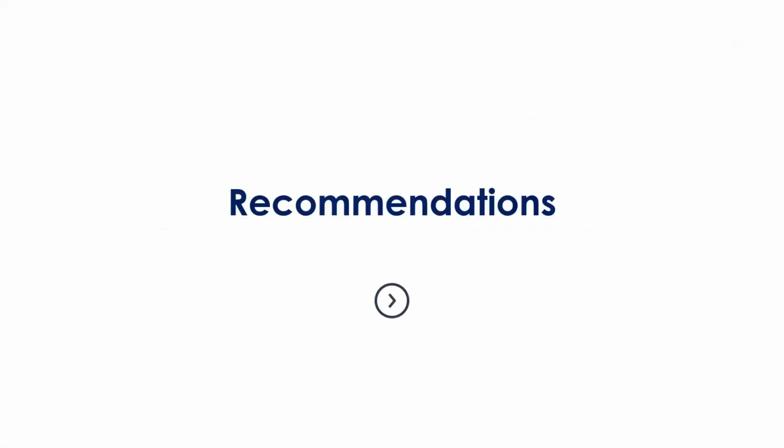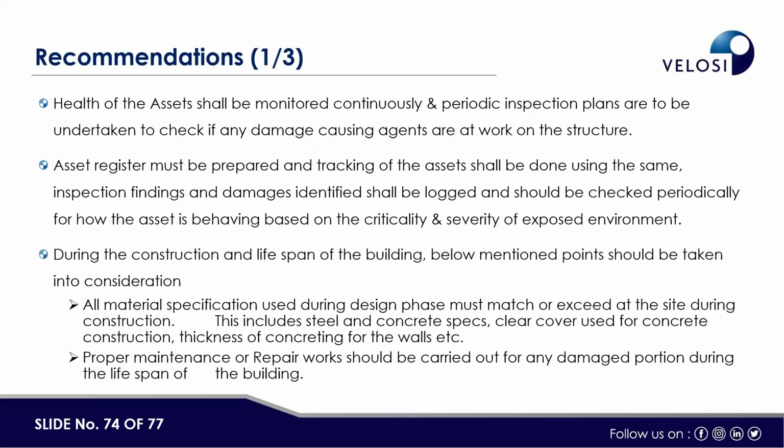Now for the study which we have conducted, these are the recommendations. The health of the asset shall be monitored continuously and periodic inspection plans are to be undertaken to check if there are any damage causing agents at work on the structure. Then an asset register must be prepared and tracking of the asset shall be done using the same inspection. Findings and damage identified shall be logged and should be checked periodically for how the asset is behaving, based on the criticality and severity of the exposed environment.